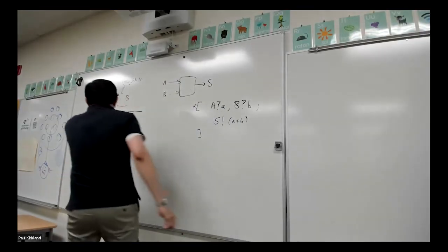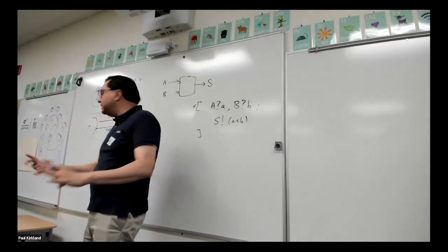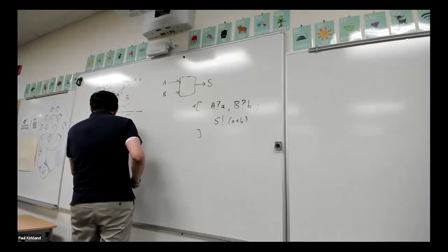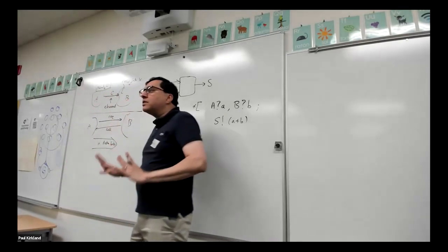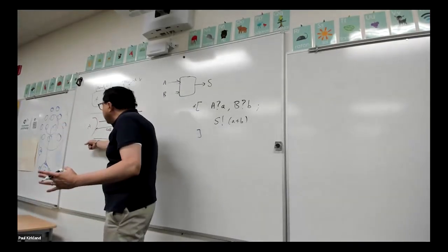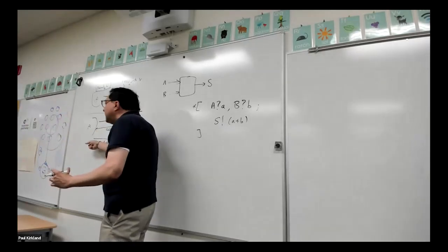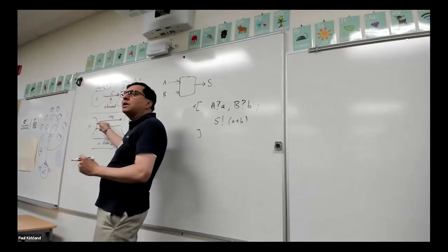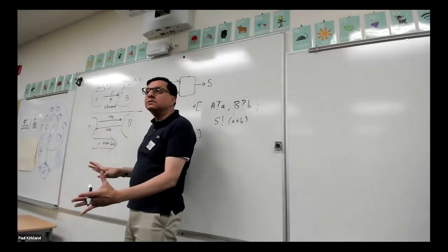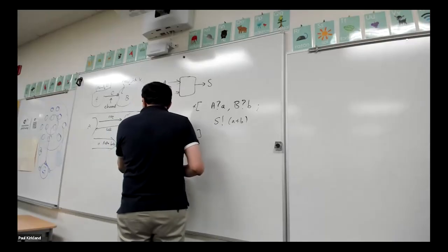Go ahead then. Anyway, so there's request and ACK. The simplest way to do data that everybody understands is I'm just going to add N data bits. Now this protocol requires timing information, and the timing information is basically when I set the data bits. The simplest variation is I set the data bits, and only then do I toggle the request. So when the request changes, the data bits have to be stable. That's sometimes called a data bundling requirement, and this protocol is called bundled data.